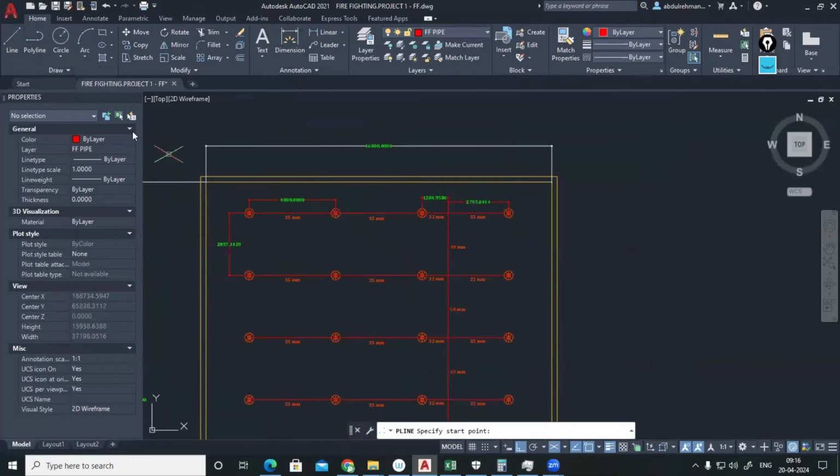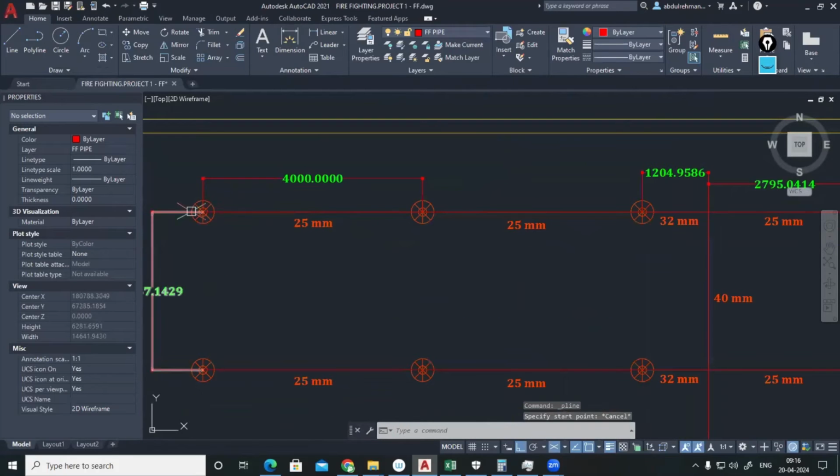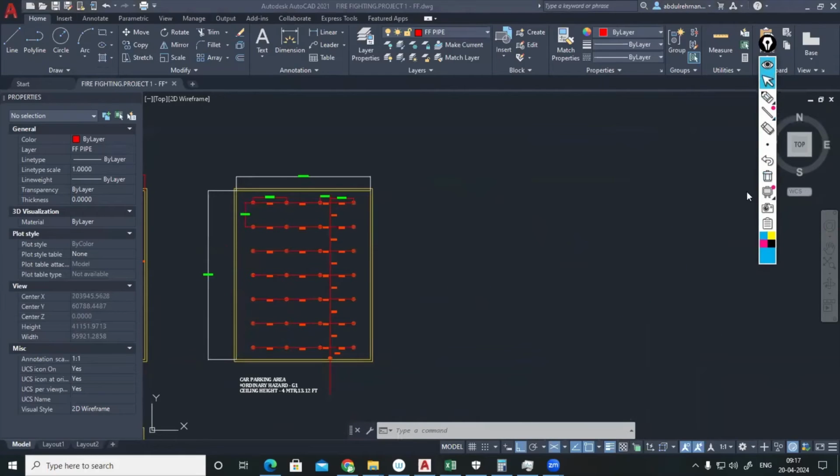The first one I am making from here. This sprinkler is called the hydraulically most demanding sprinkler. When you are doing the hydraulic calculation, for example, if you have a multi-story building and this is your riser, every floor might have a cross main, and a lot of branch lines will be connecting there. Your pump might be located on the bottom level, ground level or somewhere.